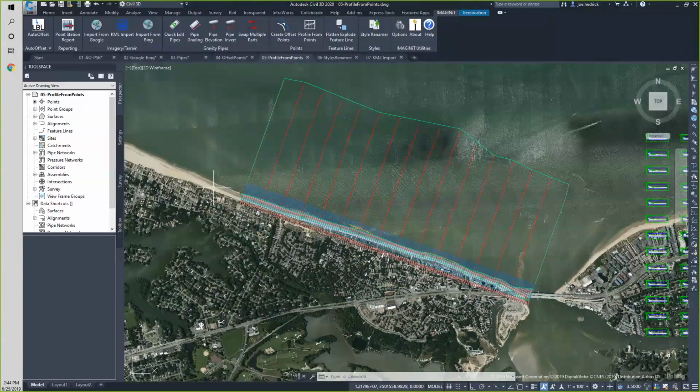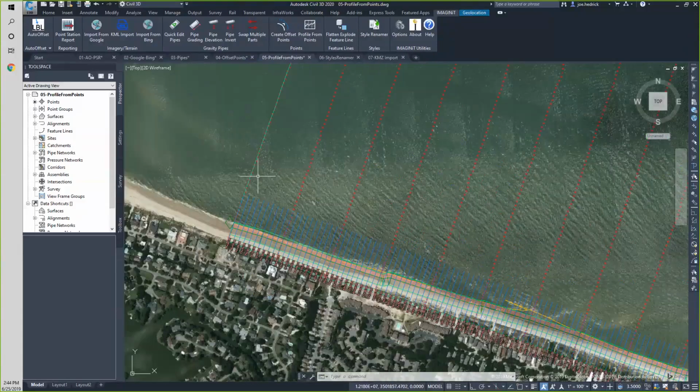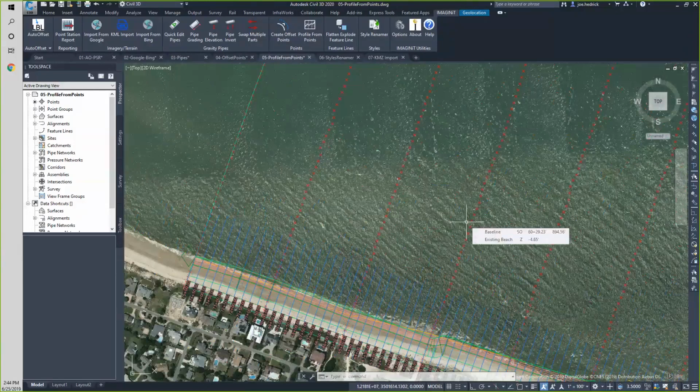Now, this particular example, I live in Virginia Beach, Virginia. This is kind of the mouth of a very, very popular inlet right where the Chesapeake Bay meets the Atlantic Ocean. And there is a tremendous problem of shoaling in this area. So what happens is about every 3 weeks or so, the city of Virginia Beach takes soundings all along this area, to make sure that the waterway has minimum depths, et cetera. So what you're seeing, all these little red X's, are soundings.